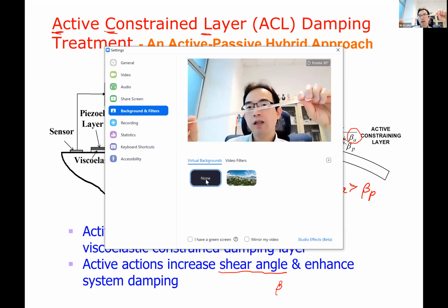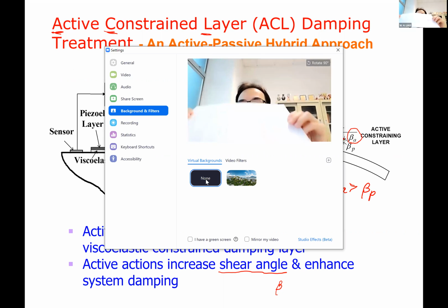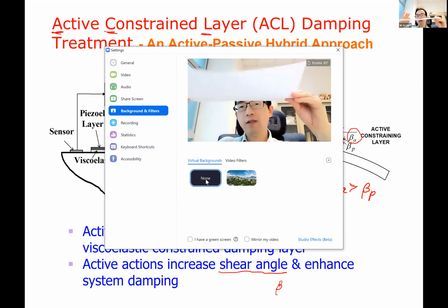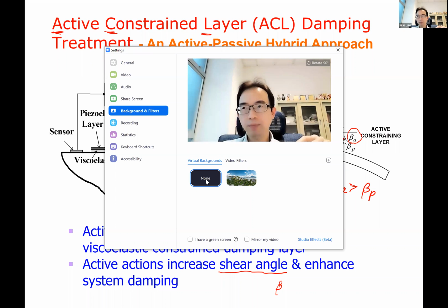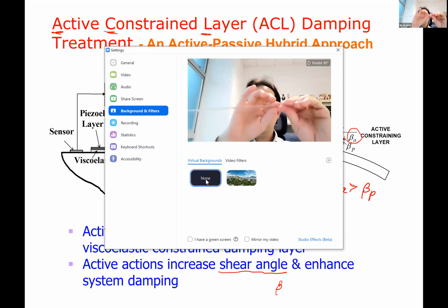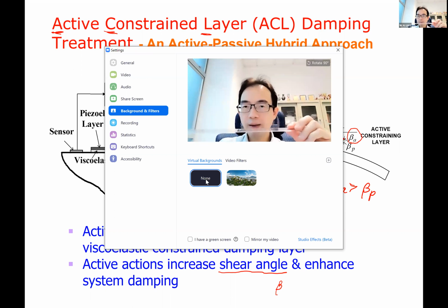Now if you extend it to 2D, not just X but also another direction, like a paper, if the paper is not that soft, if it's very large and thicker, you can treat this as a plate. We call it a 2D structure, two-dimensional. If you consider some other, it becomes three-dimensional. So it's related to the coordinates you use. For this kind of structure, you only need one spatial coordinate X along the beam. We call it a one-dimensional structure.